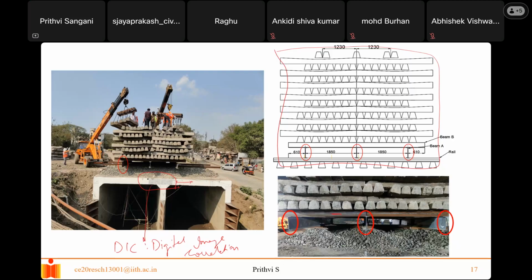This is the cutting edge which I was talking about in the starting. From the backside they keep on pushing it, so it keeps on cutting the soil and moves forward. Everywhere now, wherever you see RUB constructions, they'll use this technology. Even in Hyderabad, near Secunderabad, there are three box girders, just in front of that Rail Bhavan, Railway Bhavan.